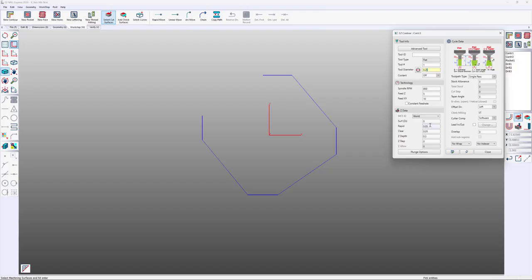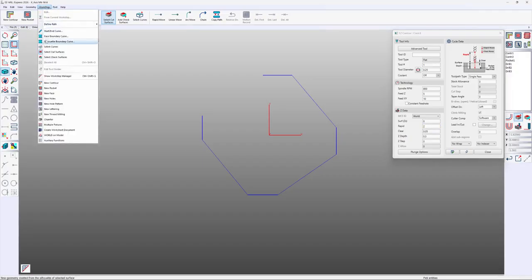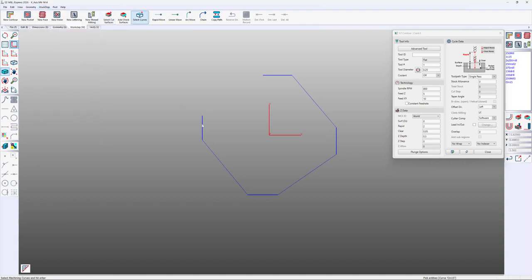And you would adjust your rapid to go over those clamps, so 2 inches above. I would have done that with the other operations as well. So now we're going to go to work step, select curves, and we're going to add that to this operation. Verify.